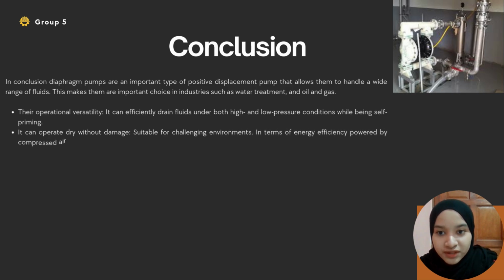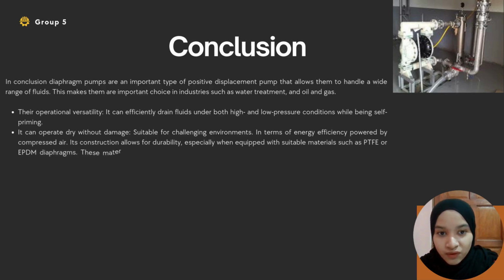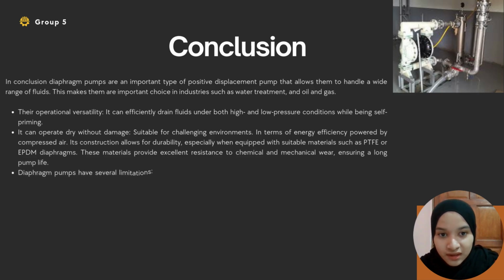One of the important advantages of diaphragm pump is their operational versatility. It can efficiently drain fluid under both high and low pressure conditions while being self-priming. In addition, it can operate dry without damage, which is suitable for challenging environments.